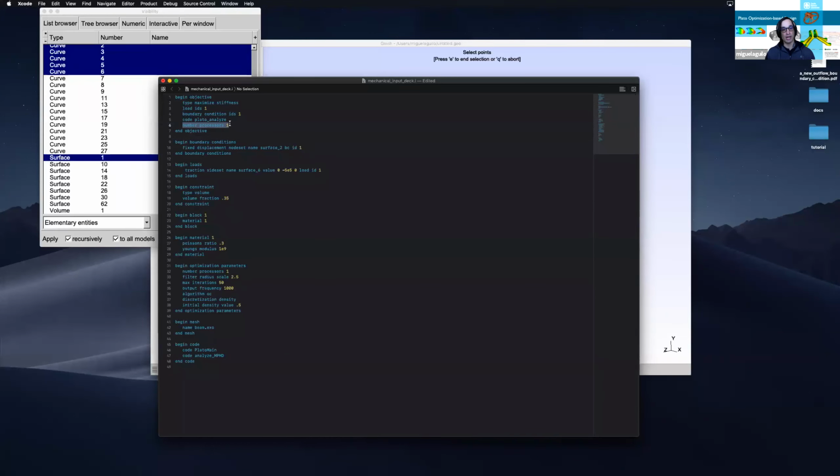And then the number of processors: we're running this on one GPU in one node, in one processor, so you assign one. But if you were to run this problem on multiple GPUs, then you would add different numbers and you can run bigger problems on multiple GPUs.